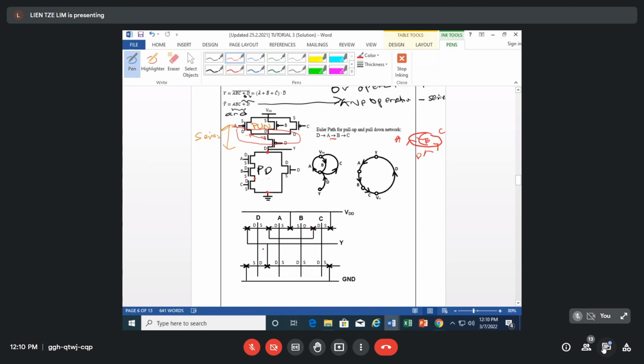You see this is D and C, right? They are not adjacent. Since they are not adjacent, we cannot draw the connections together like the previous one, so we have to draw the connections separately. One is here, this is the source terminal, drawn to connect to the ground, and this one also. And then the others we have to connect to the output at this node.